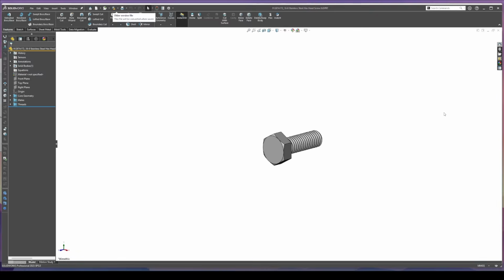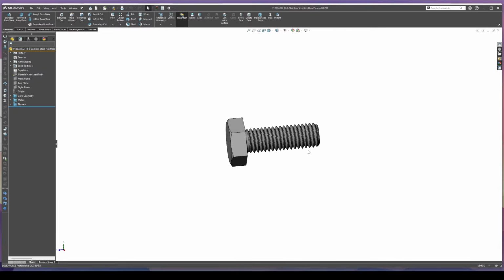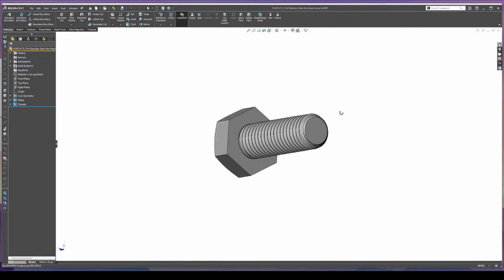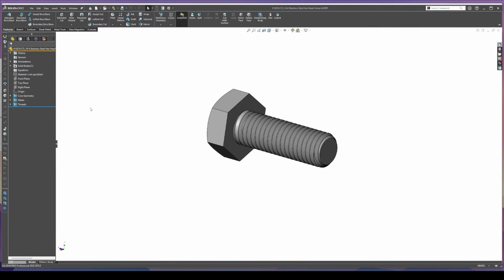What I really want to focus on in this video is that these models are not just for dropping into your assemblies, they're actually a brilliant way to learn SolidWorks. When you open one of their parts, you can reverse engineer how it was built. The majority of models are parametric, built with full dimensions, clean sketches, and sometimes even equations. You'll see features like patterns, drafts, and fillets that match real-world manufacturing.